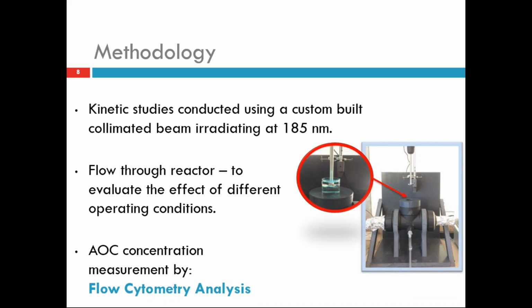It uses a bacterial cell count technique, and the AOC concentration is determined using a calibration plot, or what we call the yield coefficient. Here, the cell count is analyzed by staining the DNA of the cell with an organic dye, and thereby the flow cytometer counts the cells in the water with a fluorescent light scattering method.